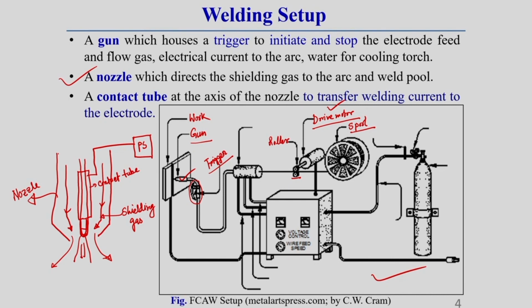Now, here generally different other types of elements are also used, that I am just labeling, then it will be very clear to you. This is the shielding gas system. This shielding gas system is sometimes required, sometimes not. Sometimes it is required for very high thickness plate, where the flux burning gas is not sufficient. At that time, we can use the extra shielding gas system.